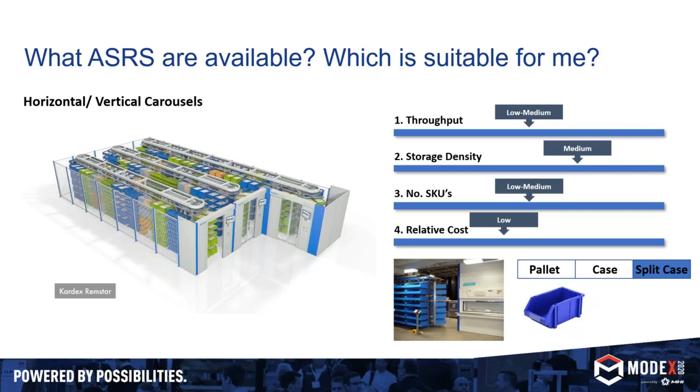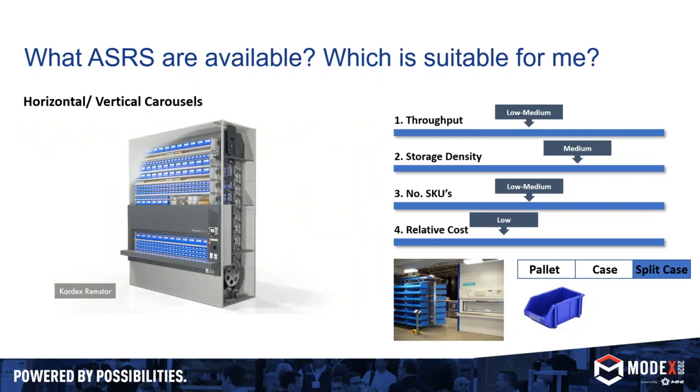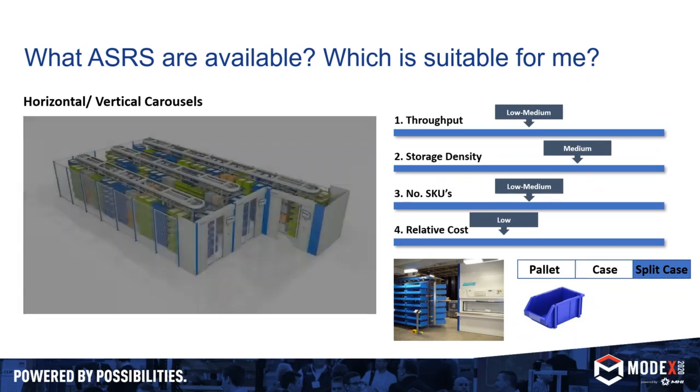And generally for lower height applications than what you would see from a vertical lift module. Vertical lift modules can go 40 foot clear, or higher, 45. Vertical carousel, you're usually not going much over 24 feet or something like that. I haven't seen too many because there's a lot of moving componentry there, and they do have to be somewhat load balanced, meaning the front end has to be similarly balanced to the back end.